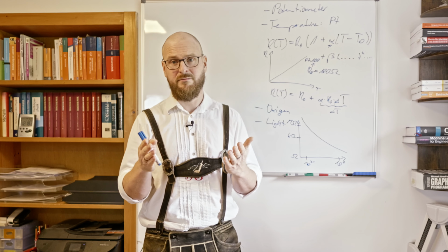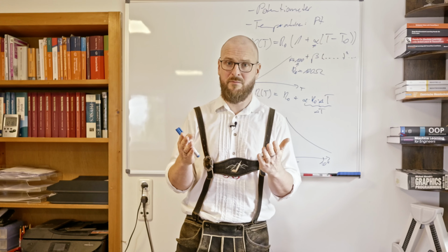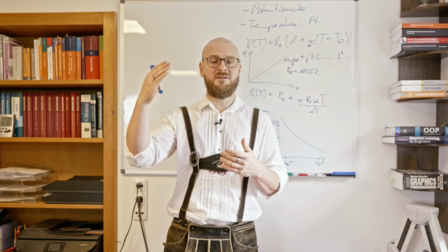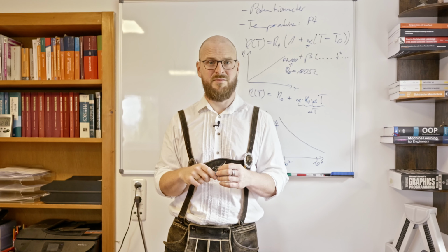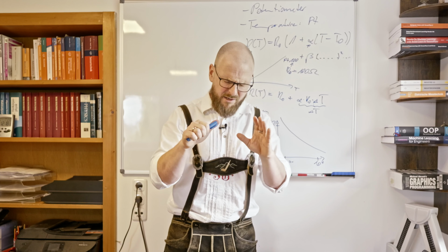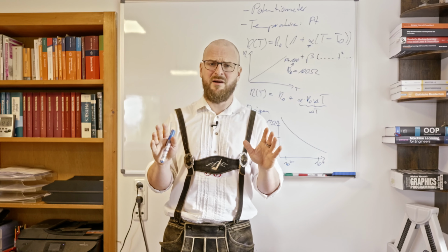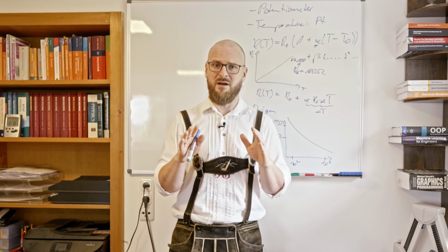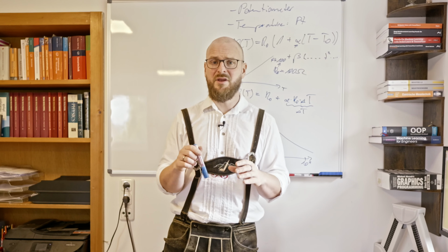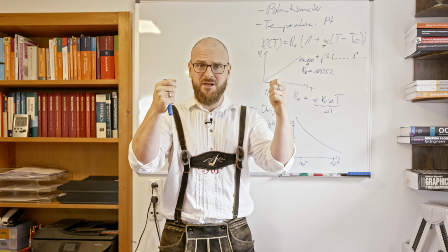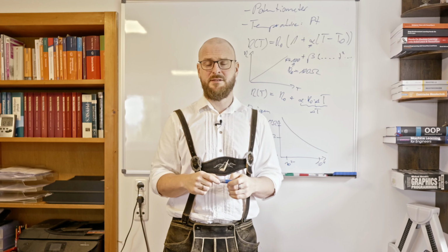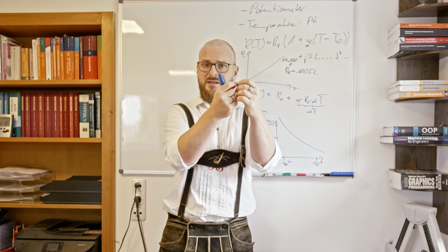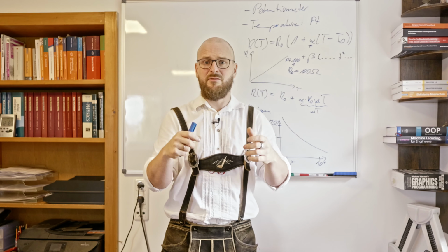Sometimes very weakly. Think of copper or platinum and its coupling to the oxygen concentration. That's very weak. There's some very, very tiny coupling we could never get to measure. On the other hand, it's very obvious that when stretching or compressing a resistance, we will change the value of its resistance.